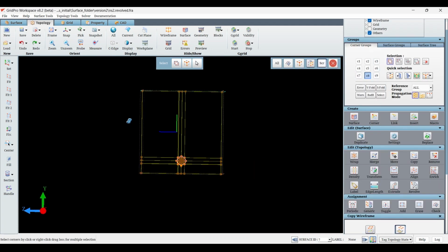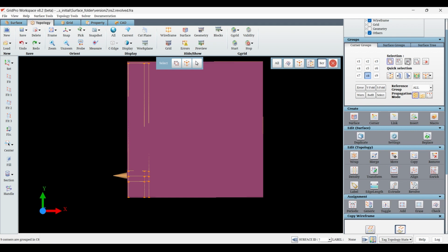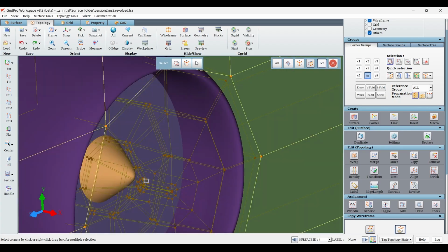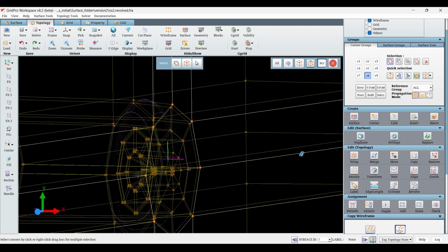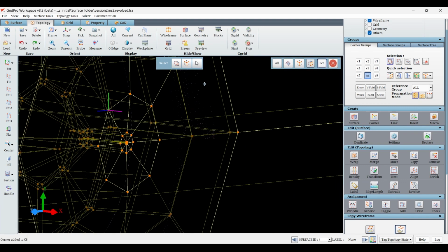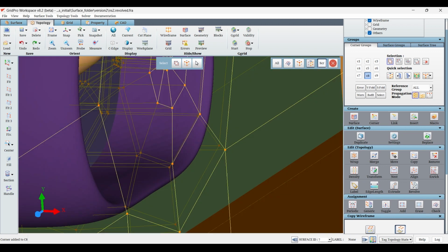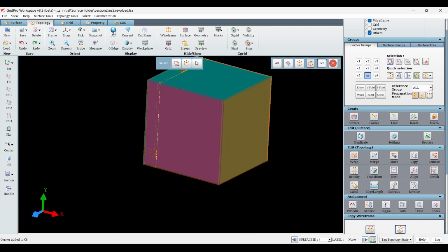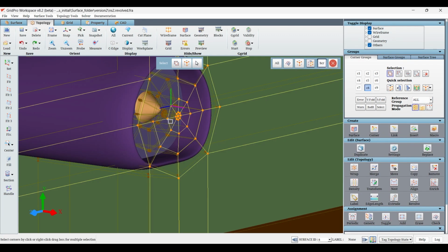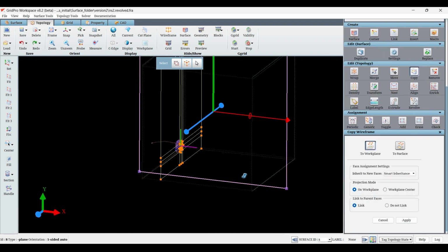Before copying the wireframe to the plane located upstream of the nacelle, the inlet, we need to group all the faces which are located in front of the nacelle, including the faces created as part of the core topology. This is then copied to the inlet.